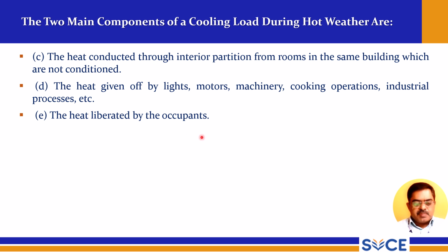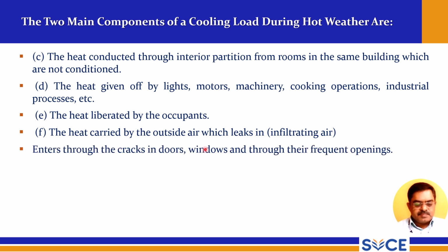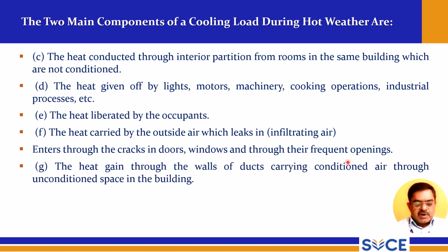The heat liberated by the occupants: even the persons sitting inside the air conditioned room exhibit heat. Then the heat carried by outside air which leaks in, that is infiltration, and enters through the cracks in doors and windows and through their frequent openings. Even if we keep opening the door, there will definitely be heat transfer from outdoor to indoor. And the heat gain